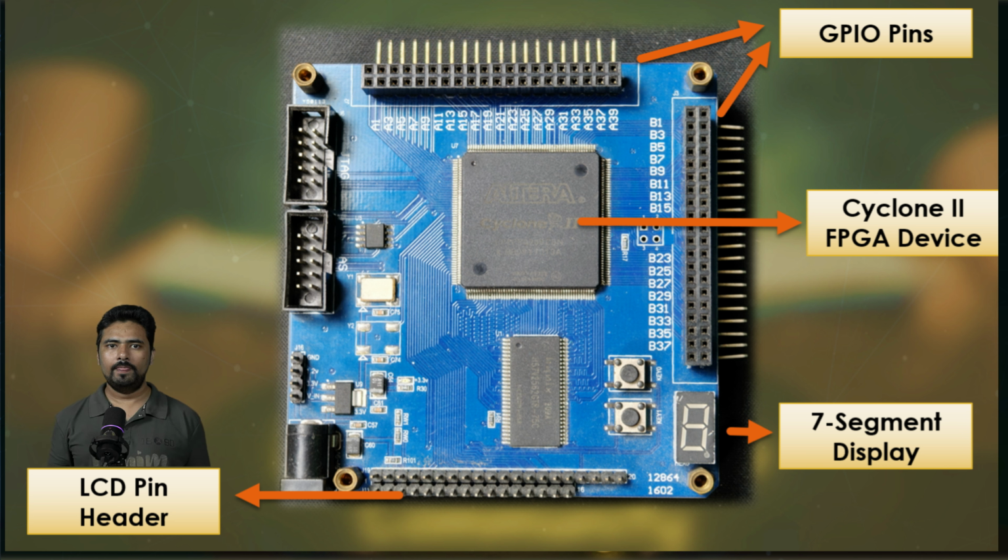We will also explore the Quartus assignment editor. This tool allows you to fine-tune the implementation of your design. While your VHDL code describes the behavior of your design, the assignment editor helps you to optimize how that code is translated into the physical hardware by the Quartus compilation process. We will also explore the other settings, options, and optimizations available within Quartus.